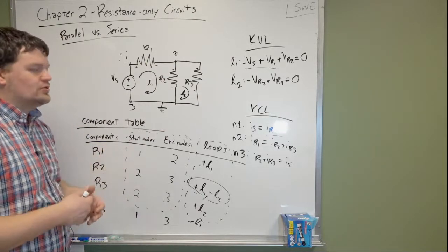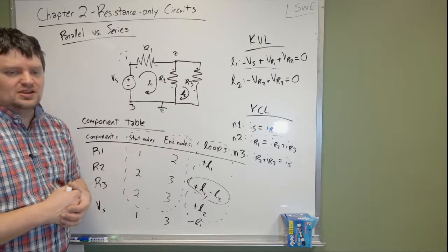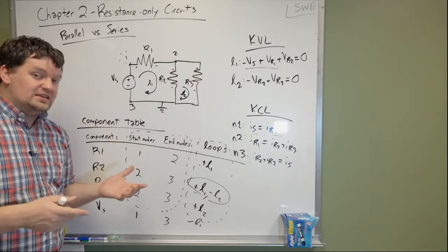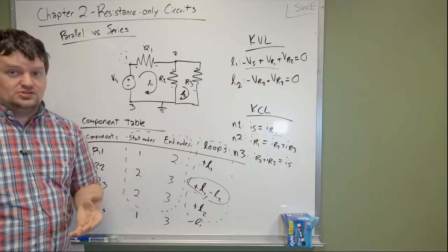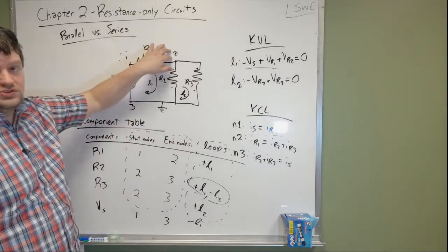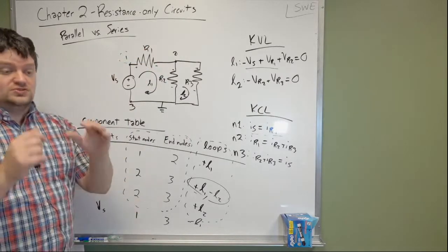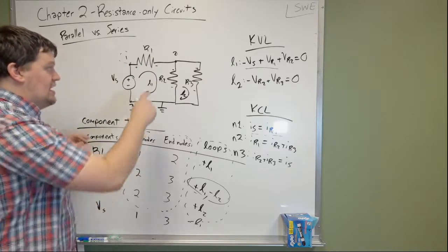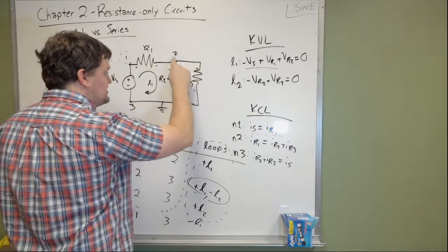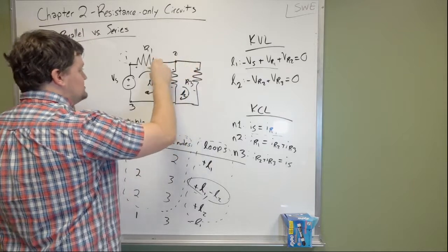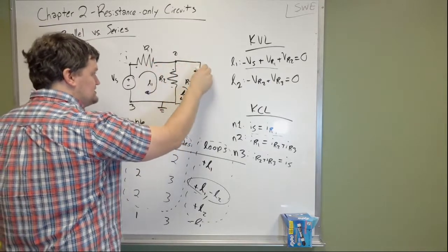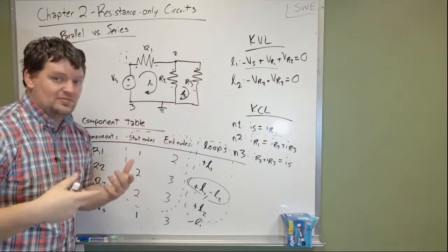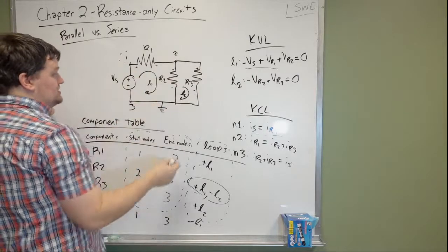So every nodal voltage is a function of time, and at some time t, it is at some voltage. You don't have two different voltages at the same node. It's one voltage, and everything connected to that node is at the same voltage. Okay, so that means the negative end of this component, the positive end here, all of them are at the same voltage because they're all connected by wires.